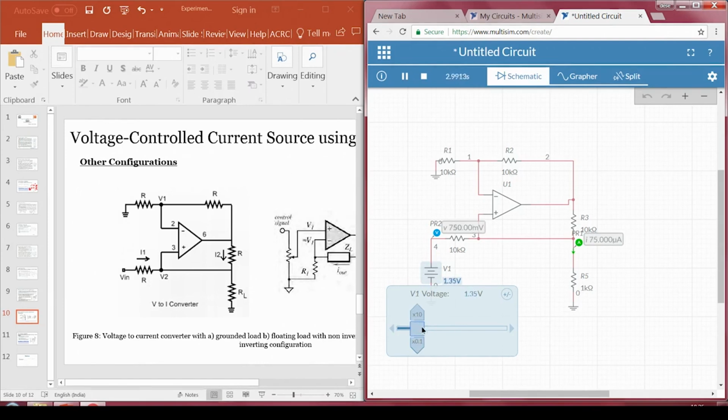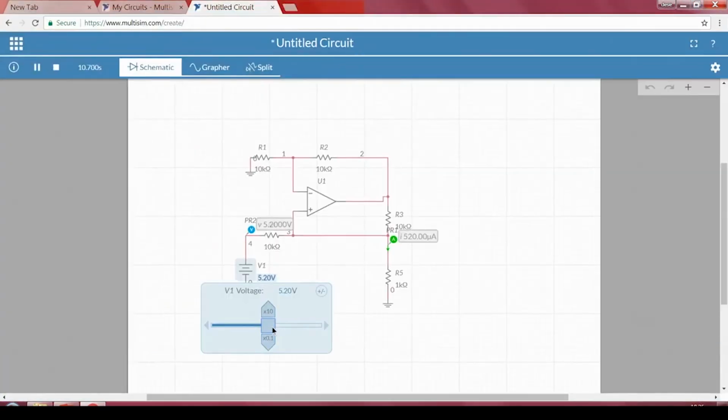and now as you see what will happen, as we change the input voltage, the output voltage follows the input voltage. Here we are measuring the current, right, voltage to current converter. You can see the output current depends on how much voltage we are applying at the input, this voltage is converted into current. It is a low current application, that is why you cannot see currents like 0.3 ampere or 0.4 amperes, right. Here you are looking at microamperes to milliamperes.